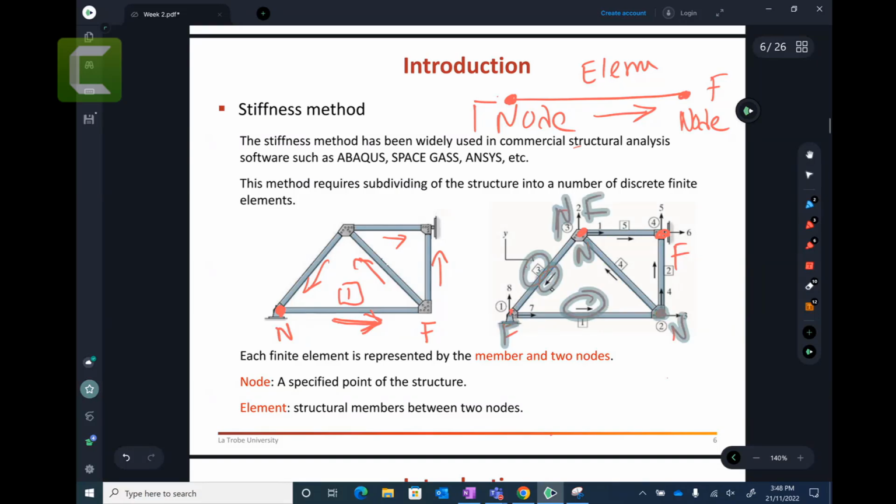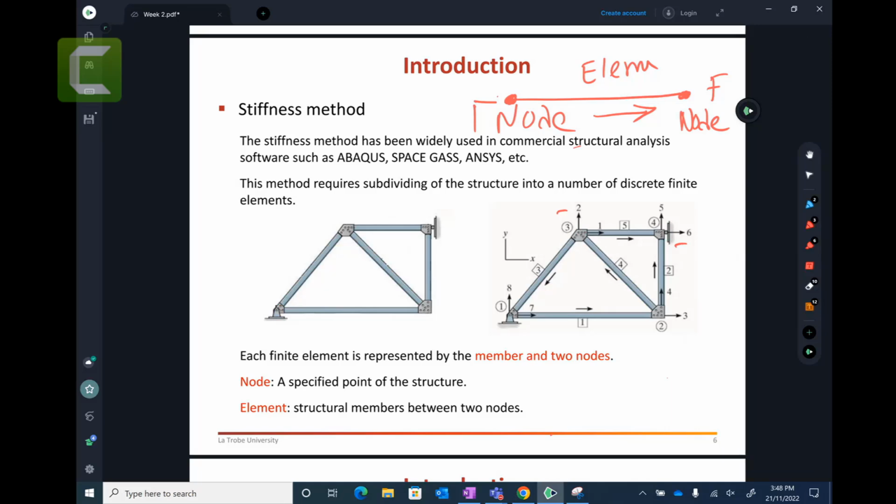So I made two things clear. The square with the number represents the element number. The arrow, the location vector, represents the element's far and near node. You can identify that. And again, both are user defined. You can put them the way you like and the answer is not going to change.